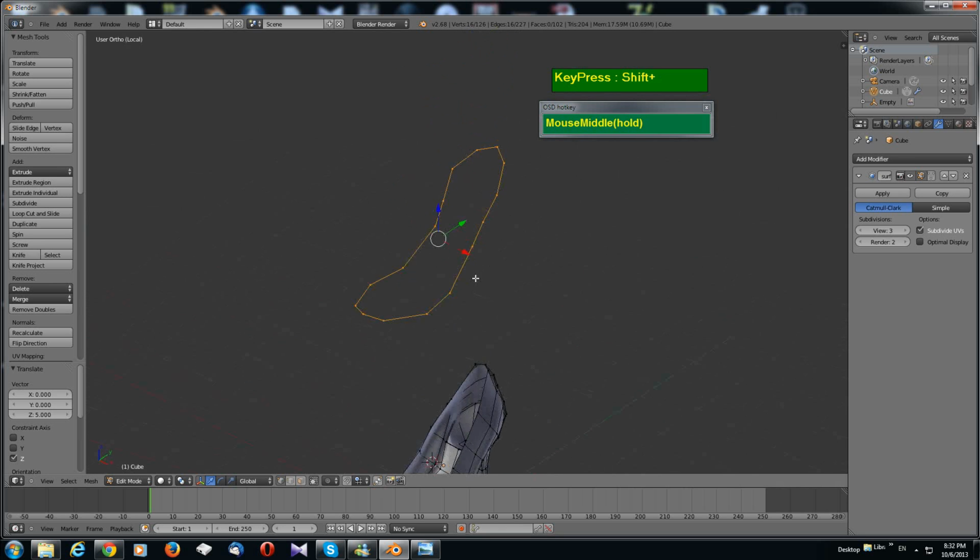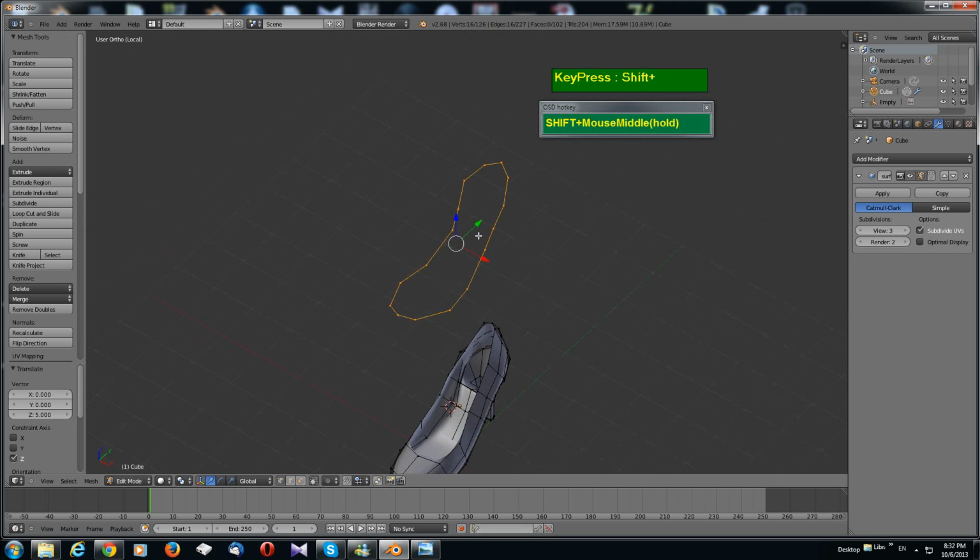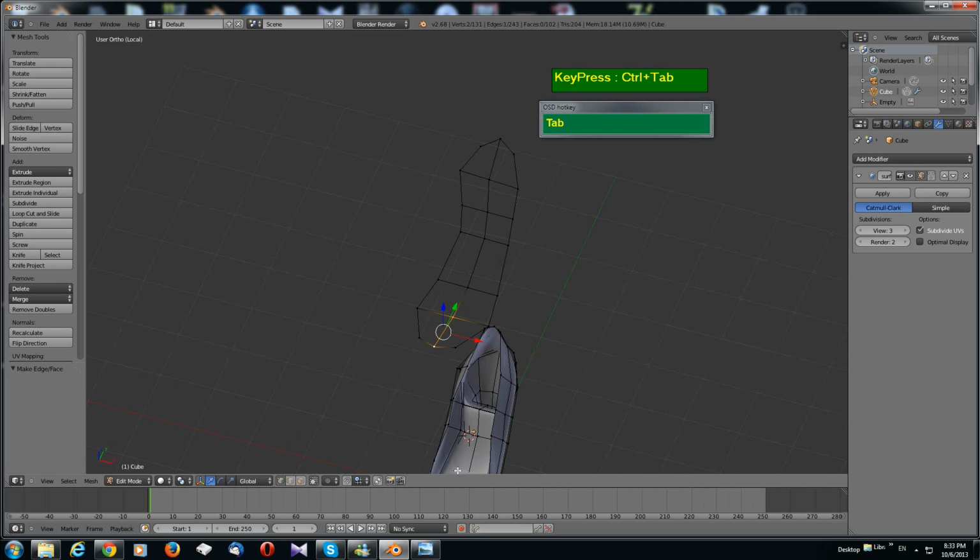I'm going to create a flat surface to form the sole. So in order to make everything subdivide properly, I'm going to select across these vertices, hold down Shift, and press F to join them together. Then I'm going to select these edges here and press subdivide, so that you can have central vertices that go all along like that. So I'm going to press F. Basically what I'm creating is another surface, another grid pattern, so that it will fit nicely into the shoe itself.